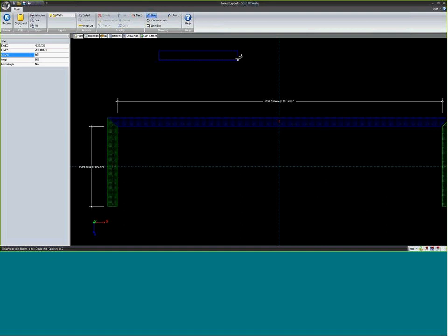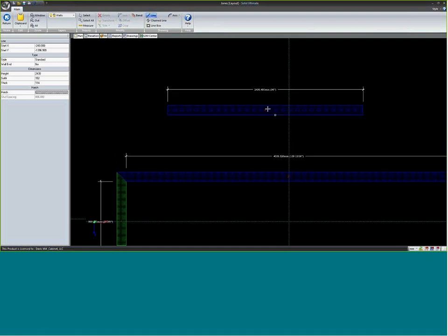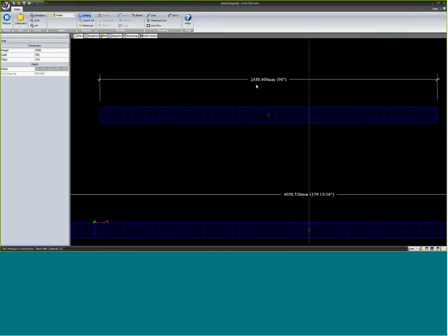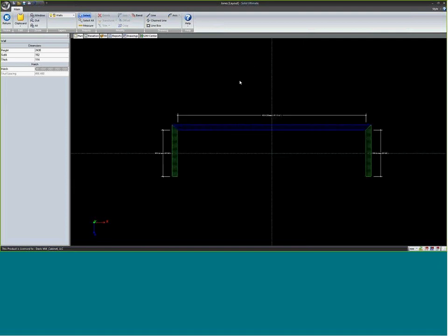If I put a multiply by 25.4 right there in the length cell and then press enter, it did the conversion math in that cell for me. So that's a way to draw in millimeters but use the inches you're used to in the process.